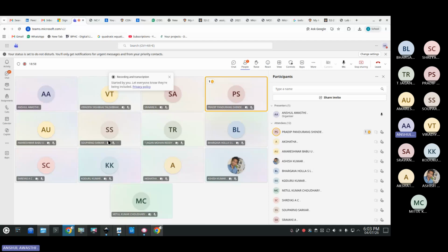If we want to see the variation in the current with respect to different temperature values, what you can do is give some variable to the temperature and assign the minimum value and maximum value, whatever minimum and maximum temperature you want, and between them how many values you want. You can give that and run the simulation. You will get the current for different values of temperature. In this way, you can use the tool. Next thing is how to import it in Cadence, which we'll see in the later part of the experiment lab.